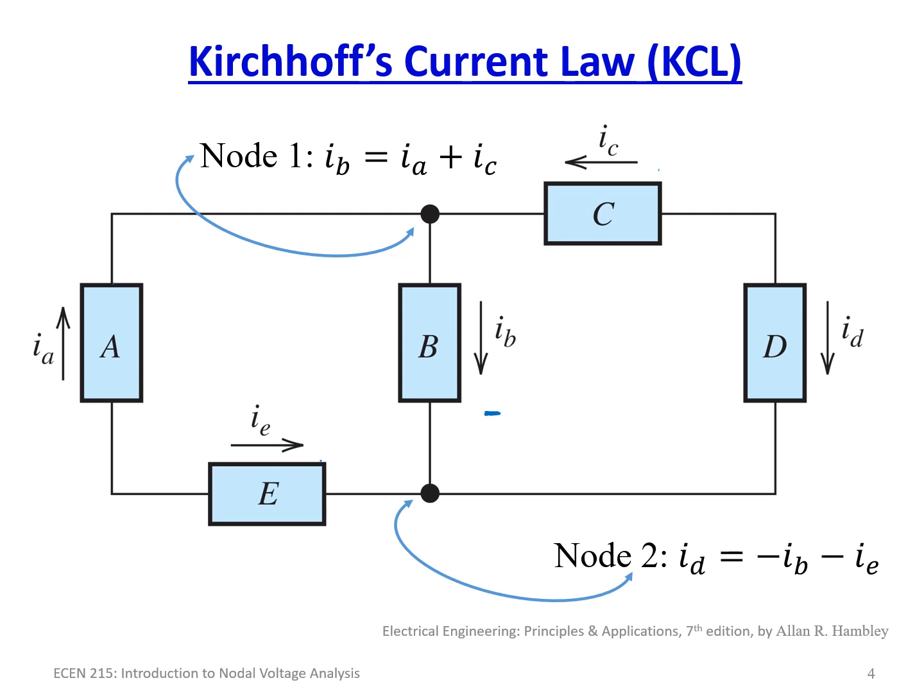And so you're going to want to measure the voltage drop across that resistive element, the sensor, and you're going to want to amplify that value and have a linear relationship that you can track with the computer and then put on the screen. Instead of putting ohms, you'll have an equation that gives you 0 psig, 1000 psig, and anything in between. So that's what we're going for here.